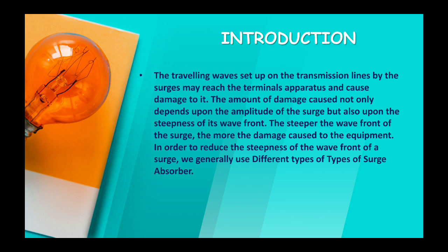The amount of damage caused depends not only upon the amplitude of the surge but also upon the steepness of its wavefront. The steeper the wavefront of the surge, the more the damage caused to the equipment. In order to reduce the steepness of the wavefront of a surge, we generally use different types of surge absorber.